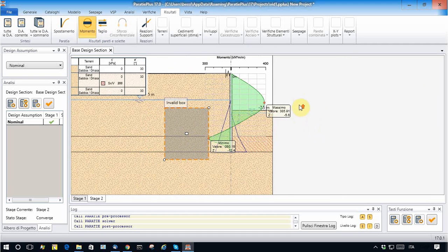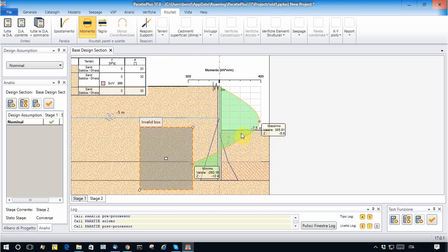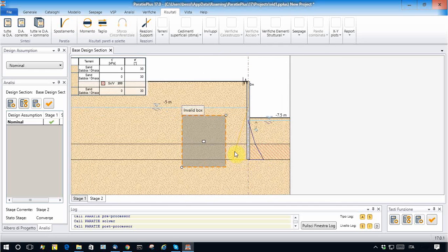So now this is the bending moment that took advantage of the fact that here we have an additional strutting contribution from the soil plug, but it is not where the bending moment is maximum. It is at the base, where the bending moments were reduced also in natural conditions. So now, why not put the soil plug just below the excavation?